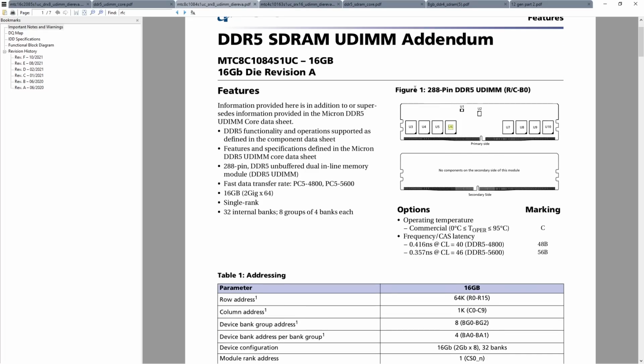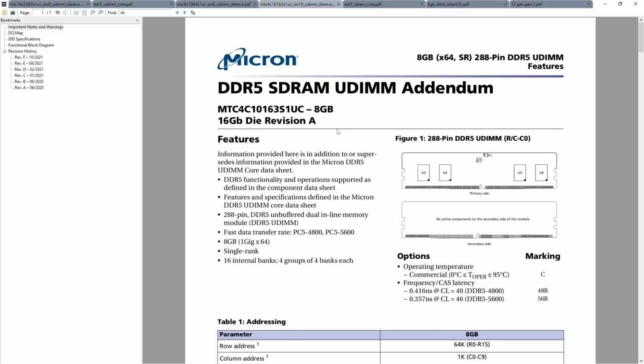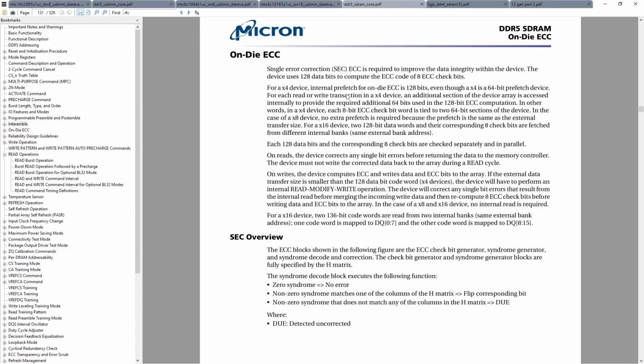The on-die error correction is literally just to deal with the fact that if the DRAM manufacturer makes a memory chip that's a bit wonky and doesn't always retain all of the information, with the on-die ECC it's still shippable as a functioning memory chip, because it'll always give you the data that you wrote to it, even if it's not actually good at storing it. So, yeah. That's the on-die ECC on DDR5, and that's basically all of the differences between DDR5 and DDR4.